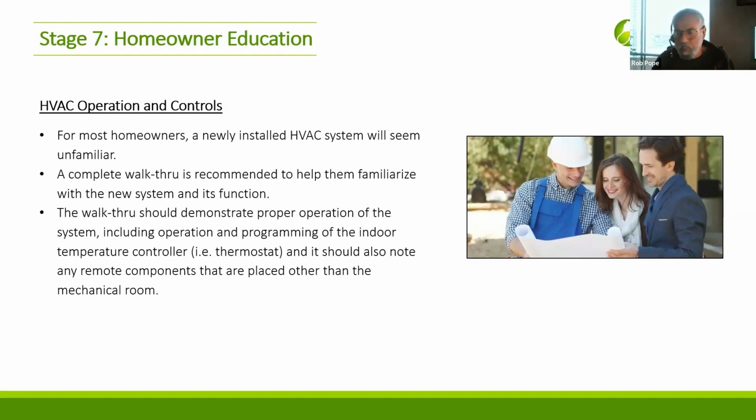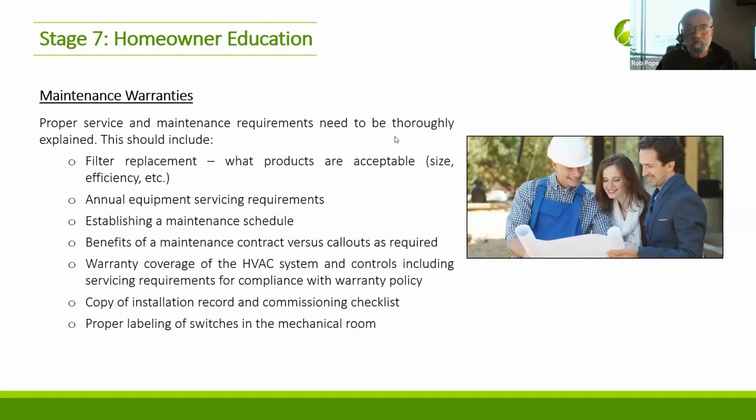These are what you can do, what you can't do for setbacks, for example. Here's the filter, here's where you change it. Make sure you clear once a year the pine needles off that outdoor unit, and have a maintenance regime available, because it's just like a car. You want to check it once in a while, make sure everything's okay, and keep it optimized.